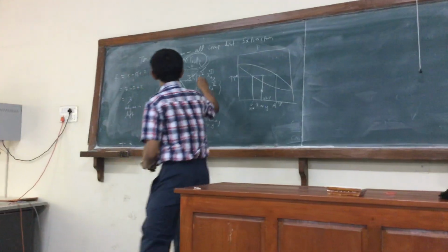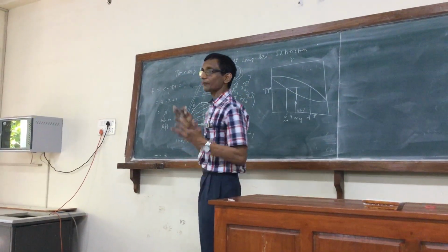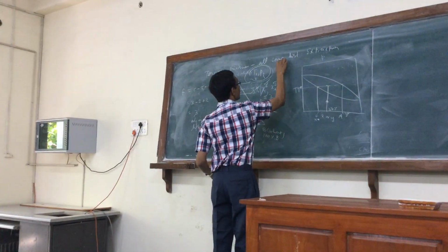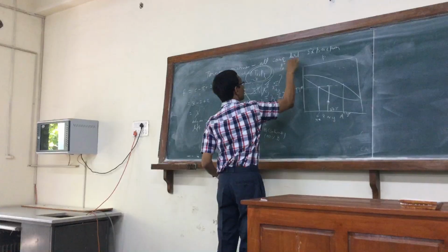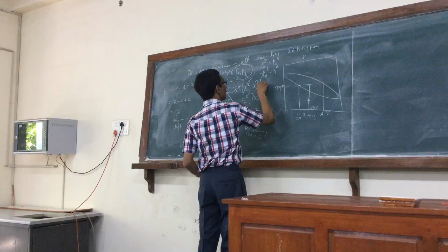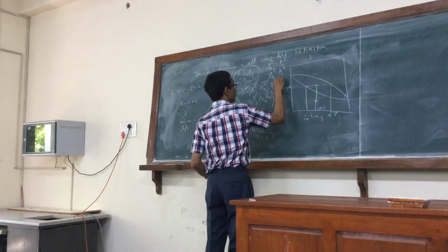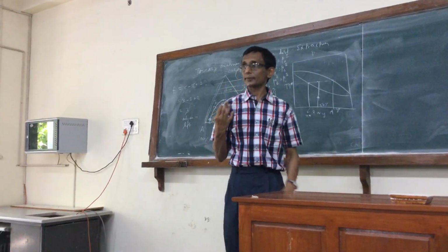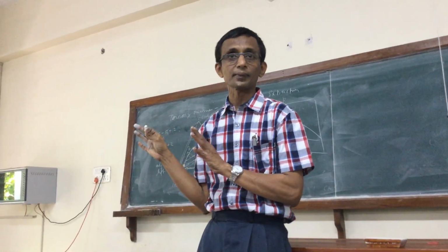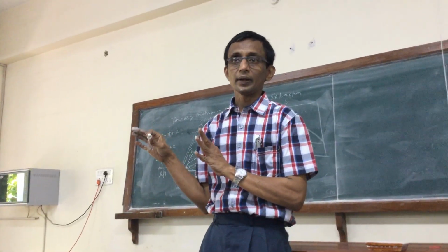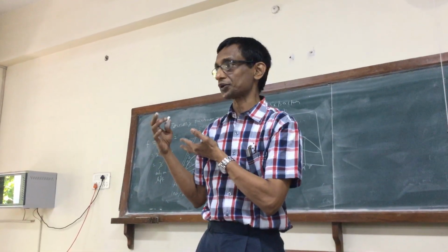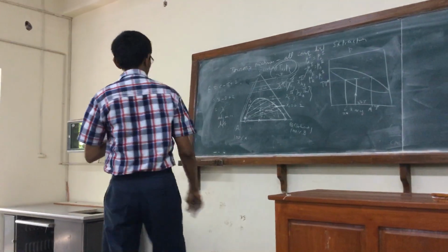So I can fix this. Now I have to determine these 3. So you have to ask, where are the equations that would determine them? Right? The equations are these: the equality of chemical potential, for all the 3 components in the 2 phases. 3 equations, 3 unknowns, so I can in principle determine the remaining variables. So the diagram is certainly consistent with it. The way we find compositions from the diagram is certainly consistent with that.